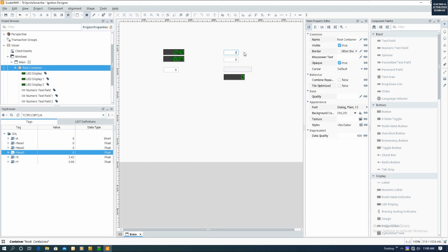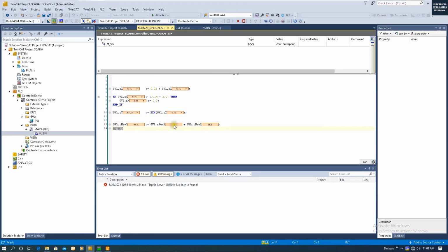So now we can type in the new 1, we can type in 10. So we can also see the 10 value showing here. So that means this variable actually changed to 10. So next one, the new 2, we can type in 56.5. Okay, so we will see the result that they add together in the logic. The new 3 equals 66.5, and this is the progress. Okay, and now if I shift to the program, so PLC will see 10 plus 56.5 equals this.